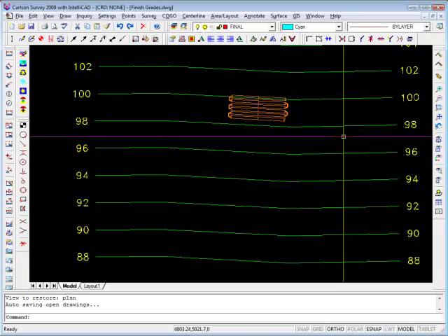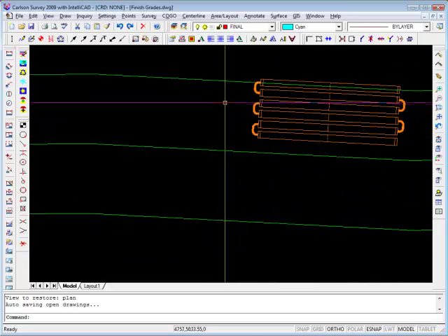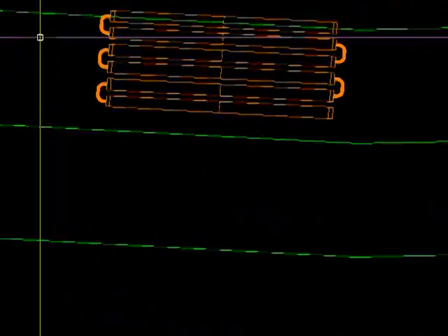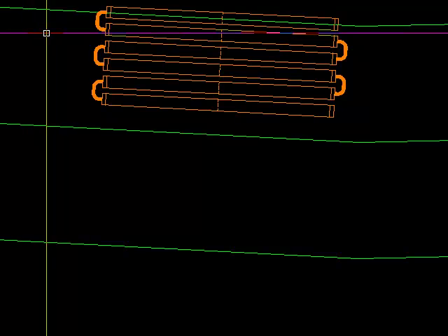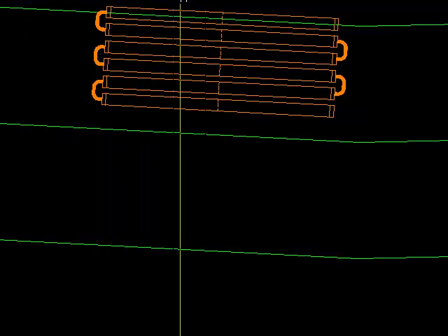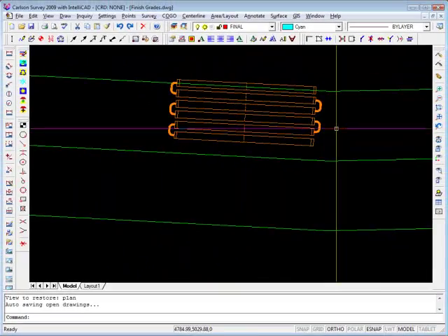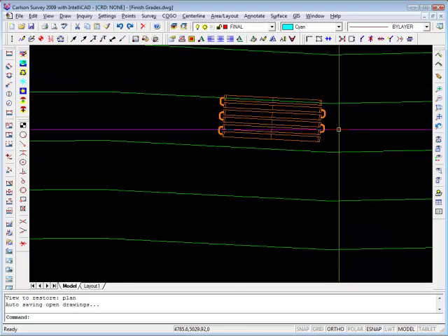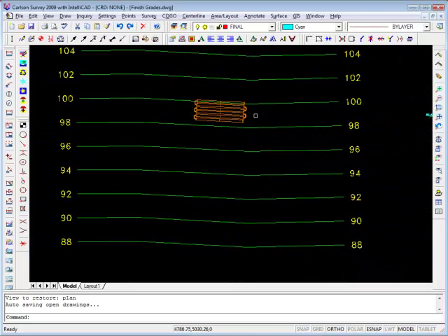Now what we have here is a pretty steep site, and I've placed an Enviroseptic field with 6 rows at the 100 contour, and you can see that the center of the top row is more or less parallel to the existing terrain. So we're interested now in finding where the finished grades will be, showing those contours for the contractor.